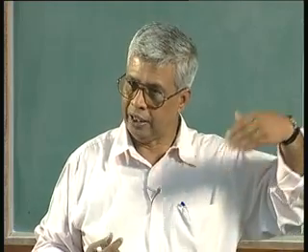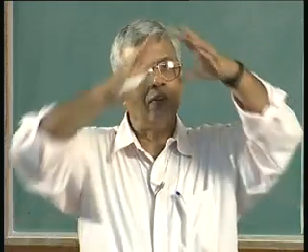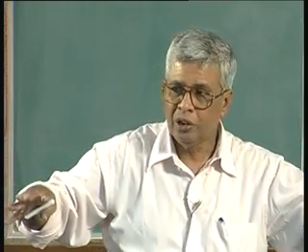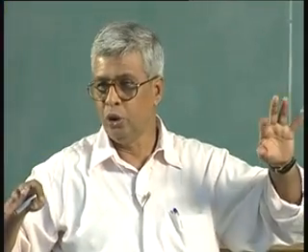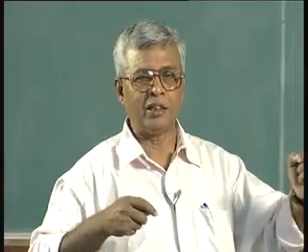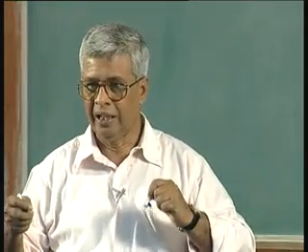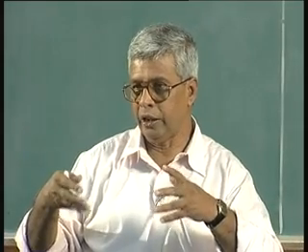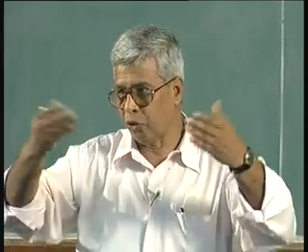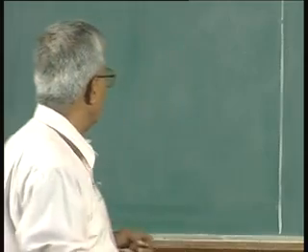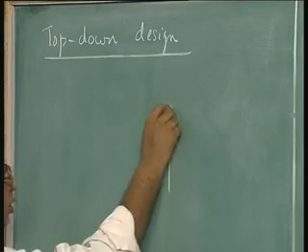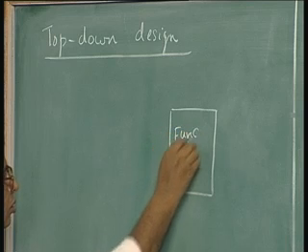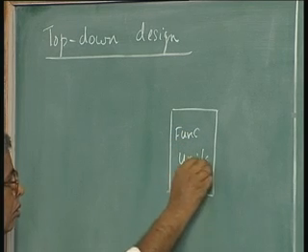That is top down, but here I am going one level above that: have an overview of what it is, what are the functional blocks required, which functional units are already available to you, which functional units have to be defined by you, and how they are interconnected in terms of timing and signals, and then try to derive the state graph. So, this is top down design in its higher level or purest form. So, what I am going to do is, any problem will have a functional unit and control unit.